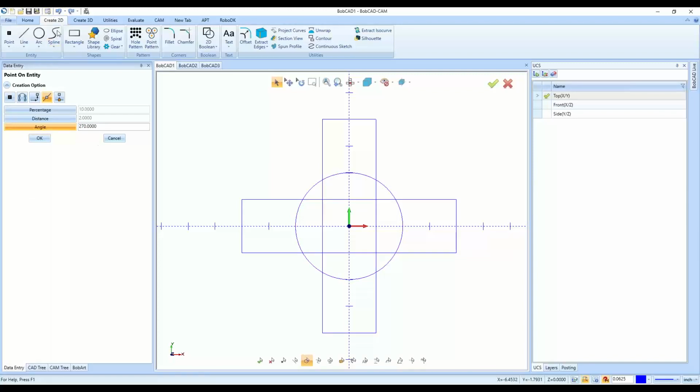And then our last option here for points is going to be point perpendicular. So I have to have a pre-existing point for this one here. And then I can select that point for my selected geometry. And then I can select certain lines or arcs, it looks like, to create a point that will be exactly perpendicular from that entity, where it's going to be on that line there. So again, I'd have to select the point, select the line, and it will go perpendicular to the point I've selected all the way across out to that line I've selected there.